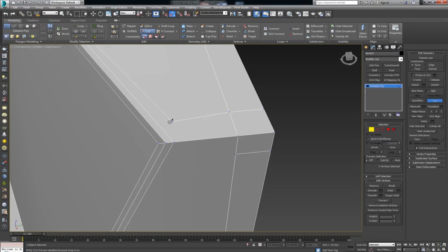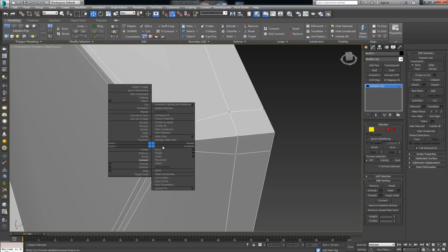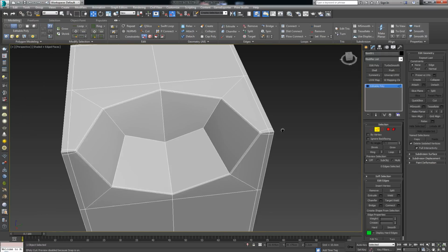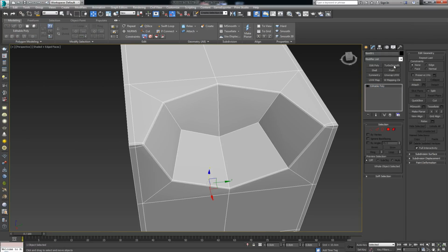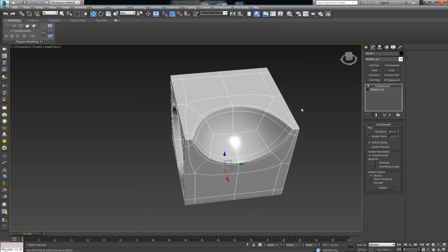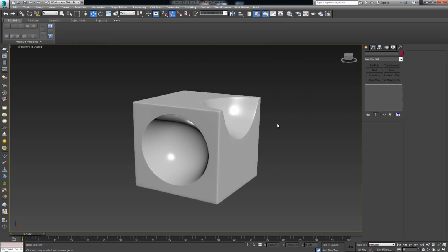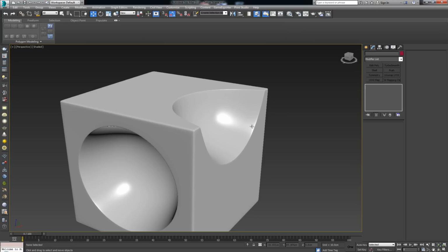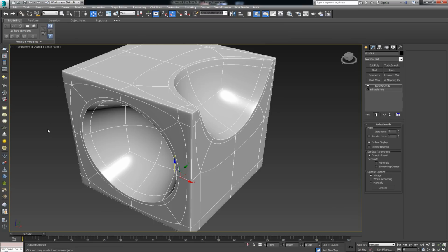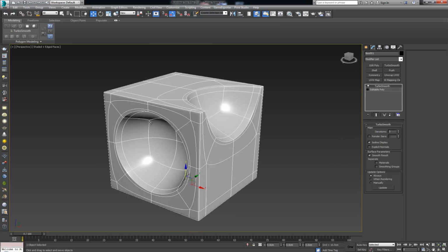Go over to the other side, cut, outer, middle, inner, middle, outer edge. Delete the one in between the inner and the middle. You're left with a diamond shape. Again, now when we put Turbo Smooth on with a couple of iterations and an isoline display, we actually end up with a geometrically correct model that has some complex shapes running across it. And with this, we're actually done.